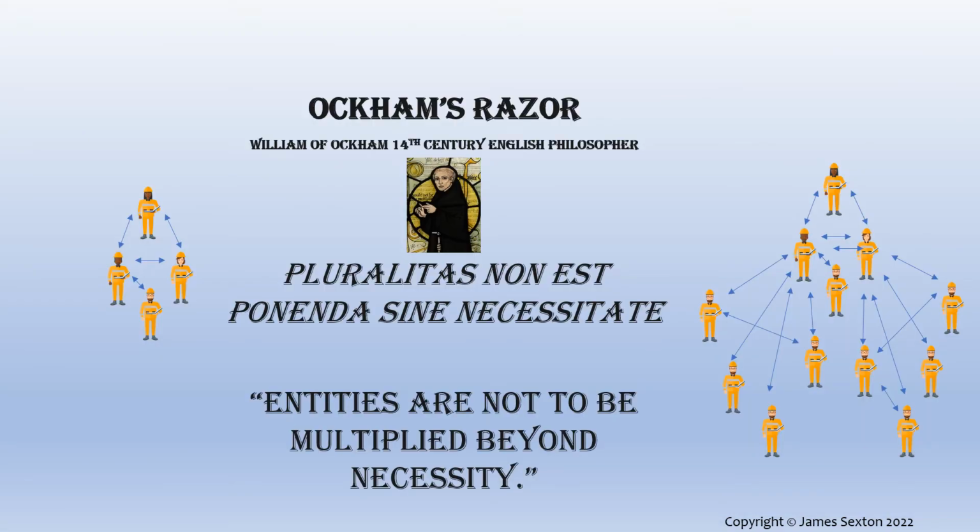A word of caution before moving on to the next topic. The physical breakdown that we have demonstrated is both necessary and sufficient. However, there's currently a trend for non-process reasons to fragment units into multiple so-called equipment modules. More equipment entities mean more interfaces, more documents, more testing, more faults, more cost, and more time.